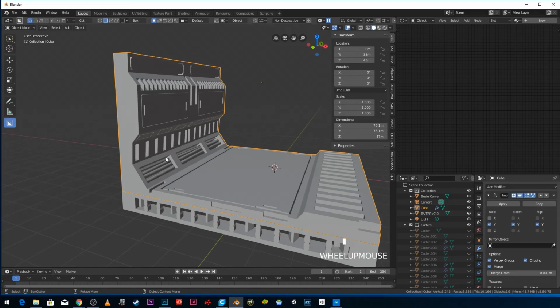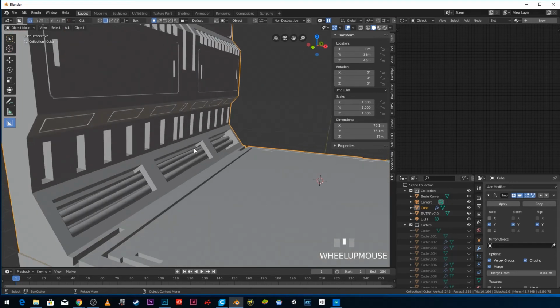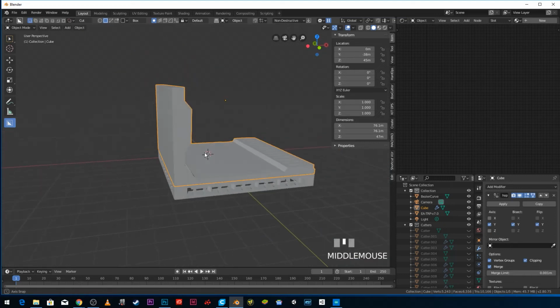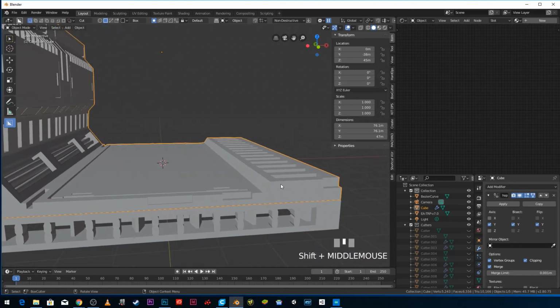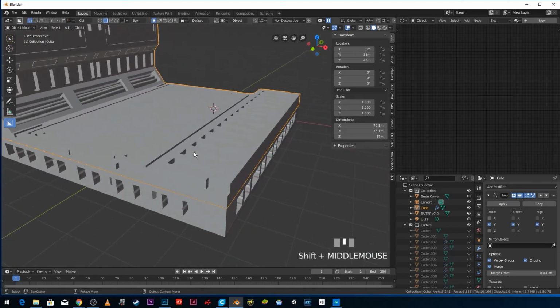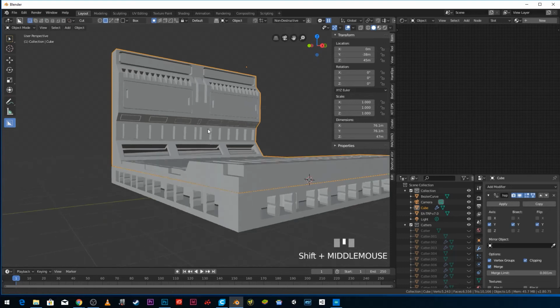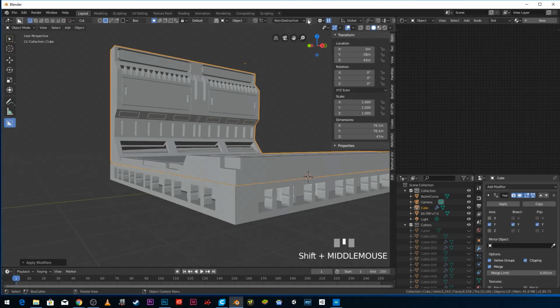Now, depending on the printer you're going to use, this may not print out well, or it may print beautifully. If it's a resin printer, it'll look lovely. If it's an FDM printer, it may struggle to print that. Now, we could do all sorts of nice things. We could cut a hole here so there's a walkway that we can look under. But again, you'll be challenging your printer to create that level of detail. So then finally, I'm just going to apply again all of them.